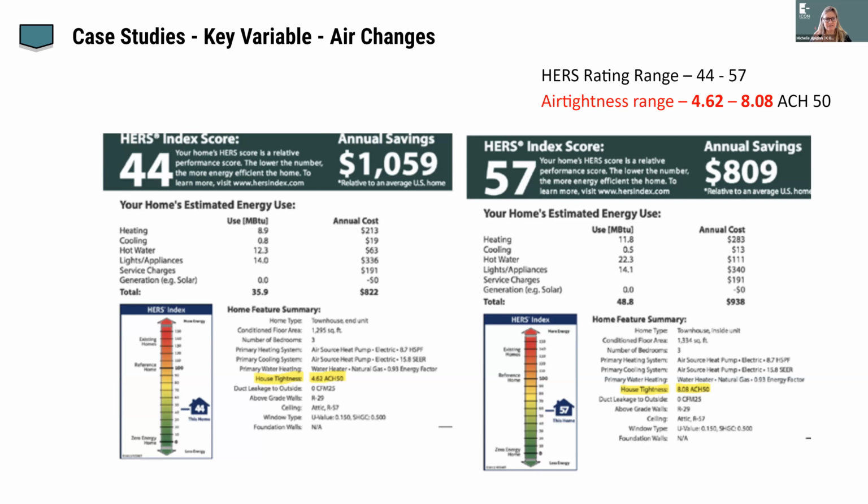And passive house has a lot of the same fundamental priorities and inputs that, as Mark described, go into Ekotrope or REM/Rate, whatever you're using to model a HERS score. It cares a lot about heating and cooling, but infiltration is really, at the end of the day, critical. And if you don't hit the low bar, or the high bar, I guess we should say, the low number that passive house expects, you just don't get there.